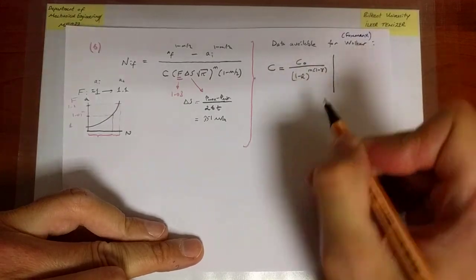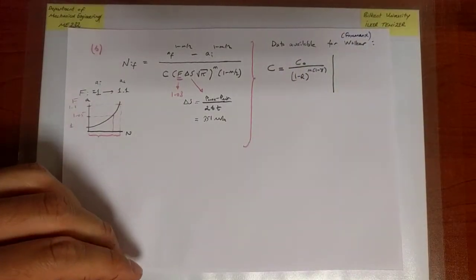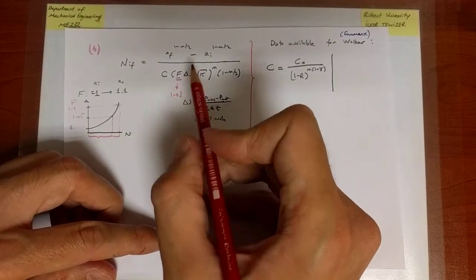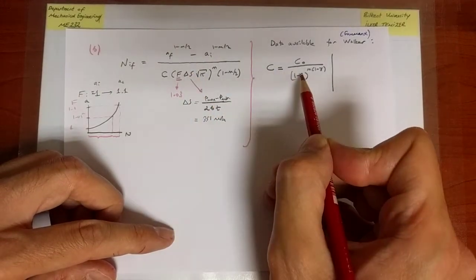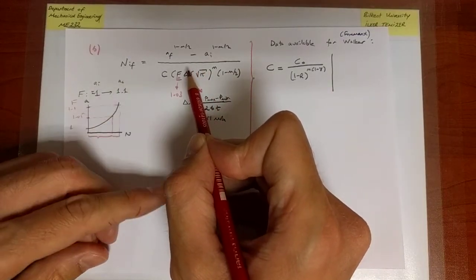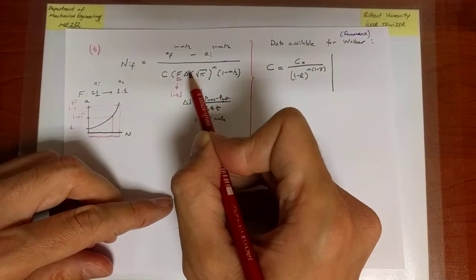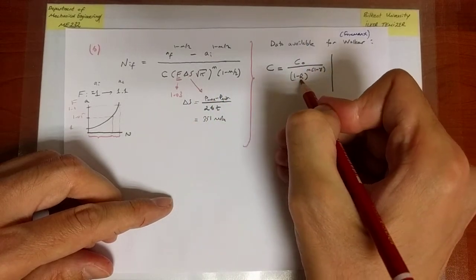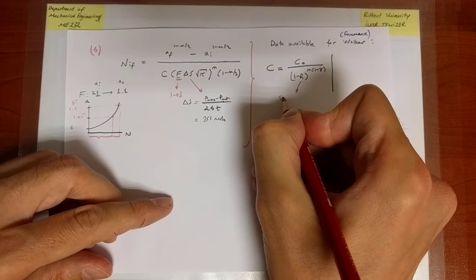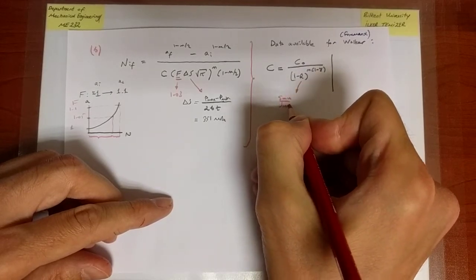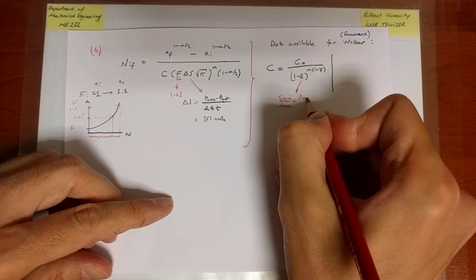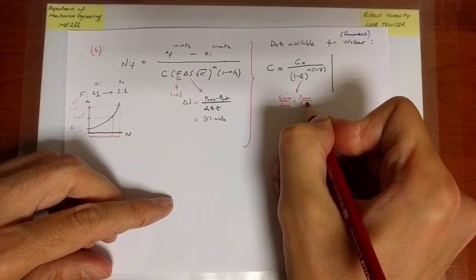So first of all, we should notice that the load profile is determined by delta S and R, or S min and S max. In this case, we're using delta S and R. So I know delta S, I just need to find R. So R is equal to S min over S max, but the area is the same for both, of course, so it's equal to P min over P max.